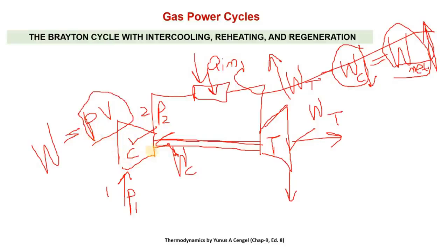So in case of compression, or the compressor, pressure is increasing and volume drops. So to reduce the work of the compressor, we cannot compromise on P, because for example from P1 to P2, this delta P is fixed, right? For a fixed delta P, if by some means we can reduce the specific volume, then the work of the compressor will drop.